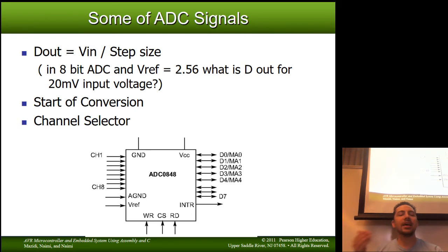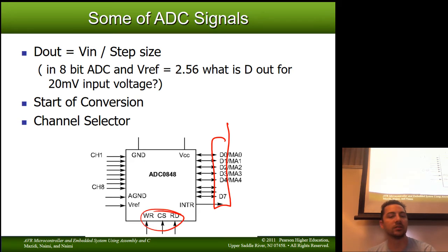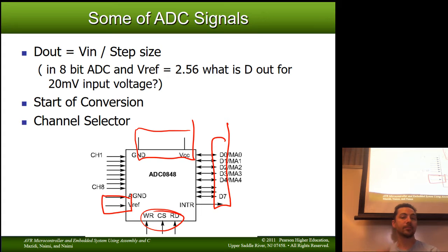It's got 8 input channels. It looks like it has an 8-bit parallel out, 8-bit parallel out right here. Okay. And it's got a few control signals and its reference. Okay. Here it's got an analog reference, but it still requires a digital supply.